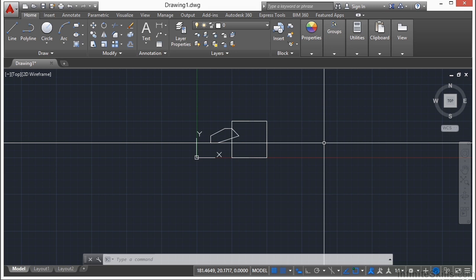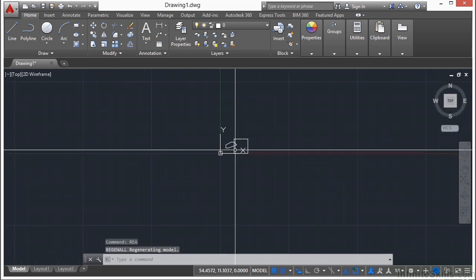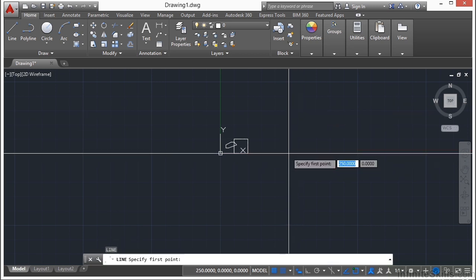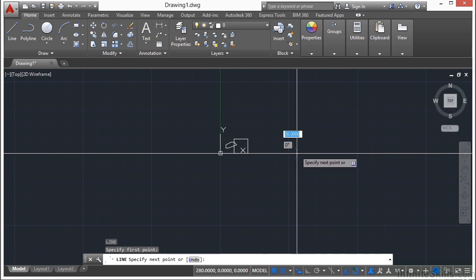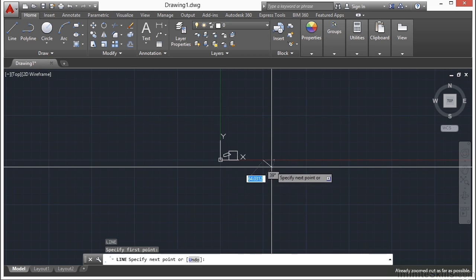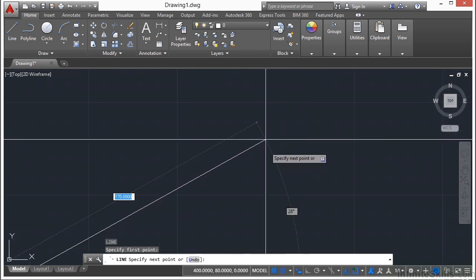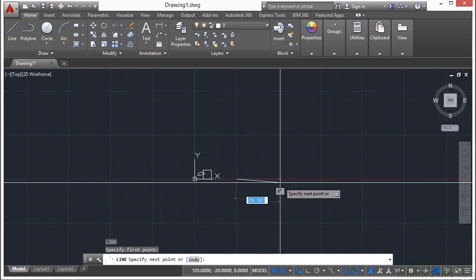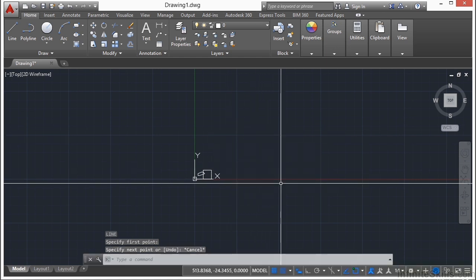Now, many users find the snap and grid features to be annoying because a lot of times if you zoom out really far, the grid changes and it's relative to your screen size. So as you can see here, I'm snapping to tens. You can tell by my units. As I move, it goes to 20, 30, 40, 50, etc. So I zoomed out enough to where the grids try to keep a sort of semi-relative size to your screen. So they're not true grid sizes. Keep that in mind. They're really just a visual guide.